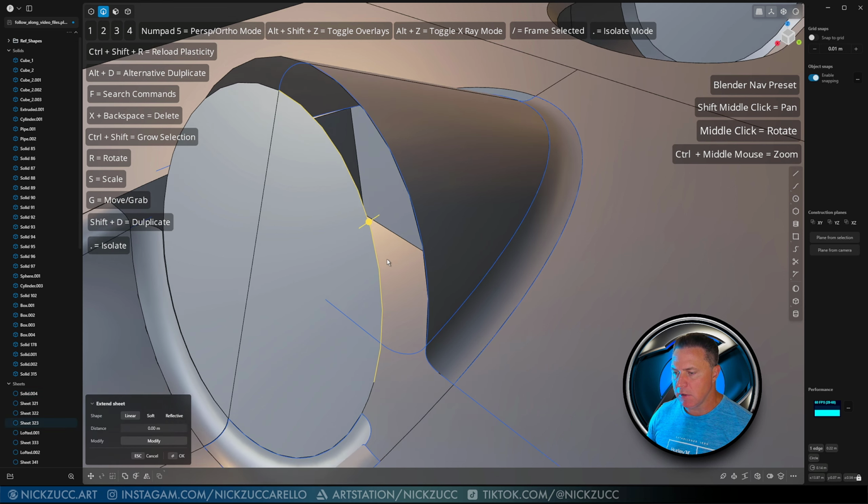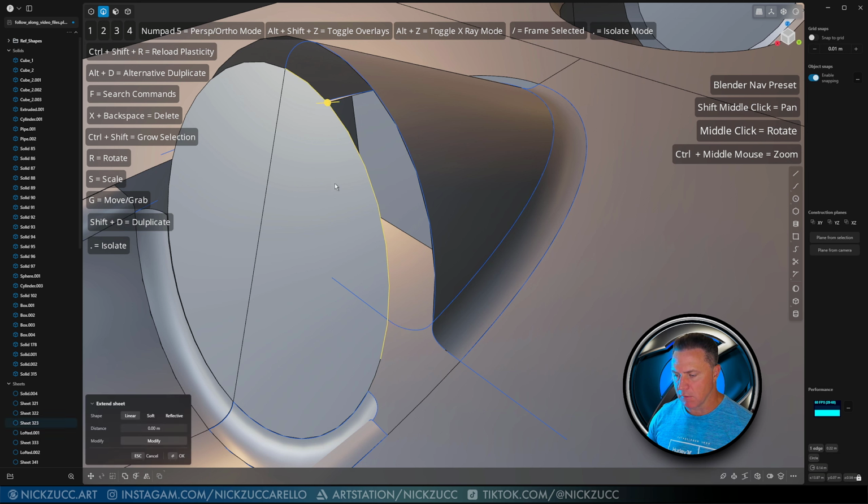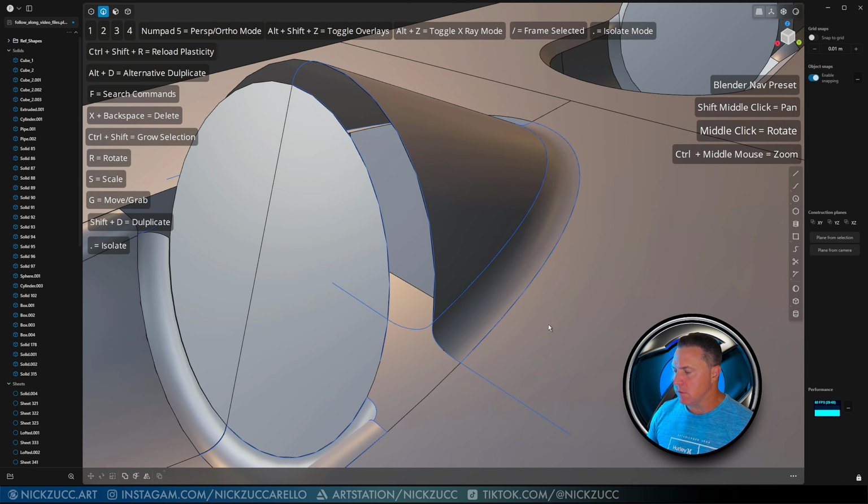And then now I do need this. I've got this curve. Got this, we need a curve here. So let's hit Shift D for that. And I really don't want that part that's on there. So we're going to be using this tool, this split curve edge at point. So we can go click right there like that. And remember to unjoin the curves, we hit Alt J.